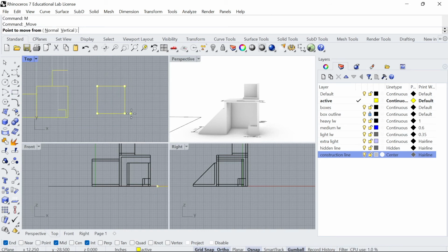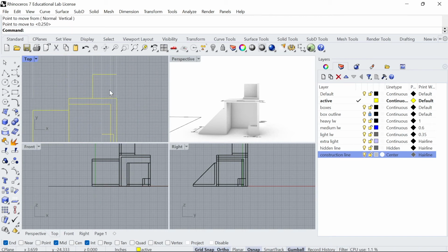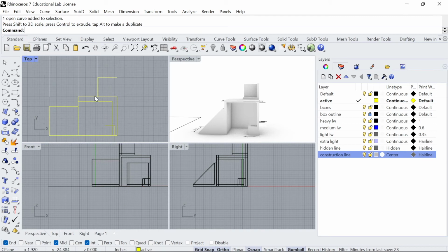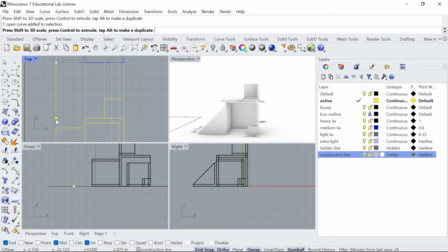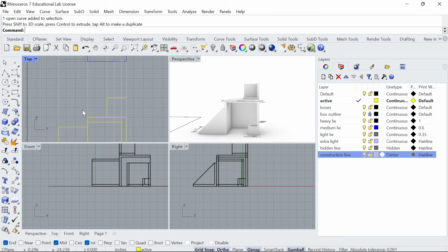And we're going to go ahead and move this. I'm going to move it to the bottom left corner of this 4-inch box because I know that's where it's actually located. And you'll see that this construction line actually does line up to it. So we know that's done properly. The construction lines help you understand that things in different views are actually aligned to one another because orthographically they are related, right? So that's why they're in alignment, and you could double check to make sure things are in the right place because the construction lines are helping you understand that.